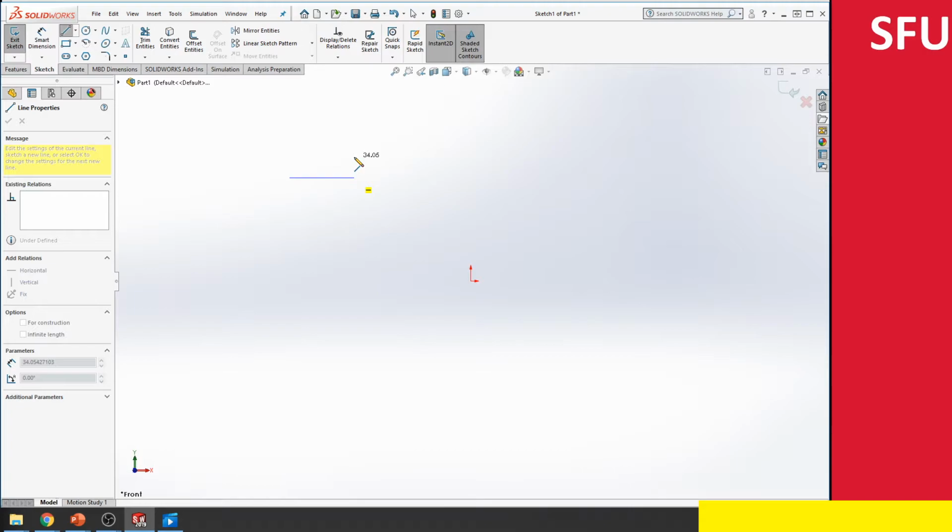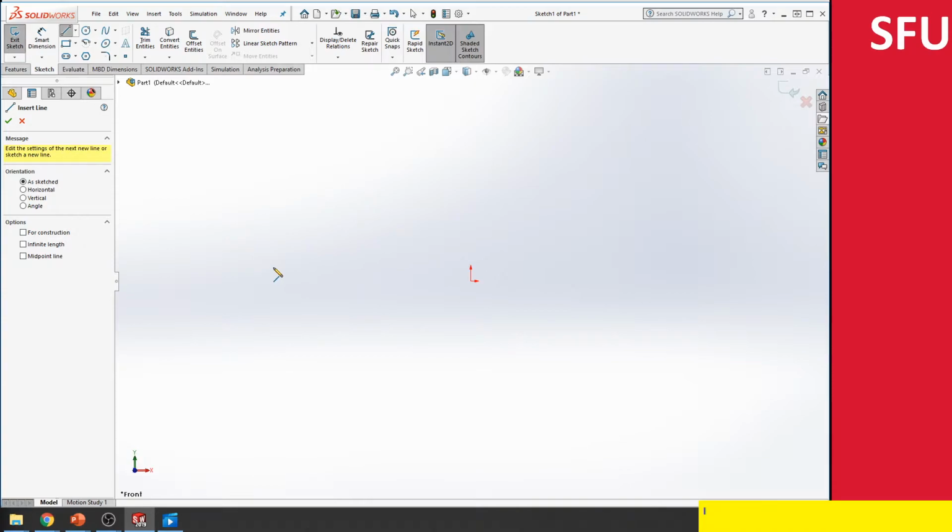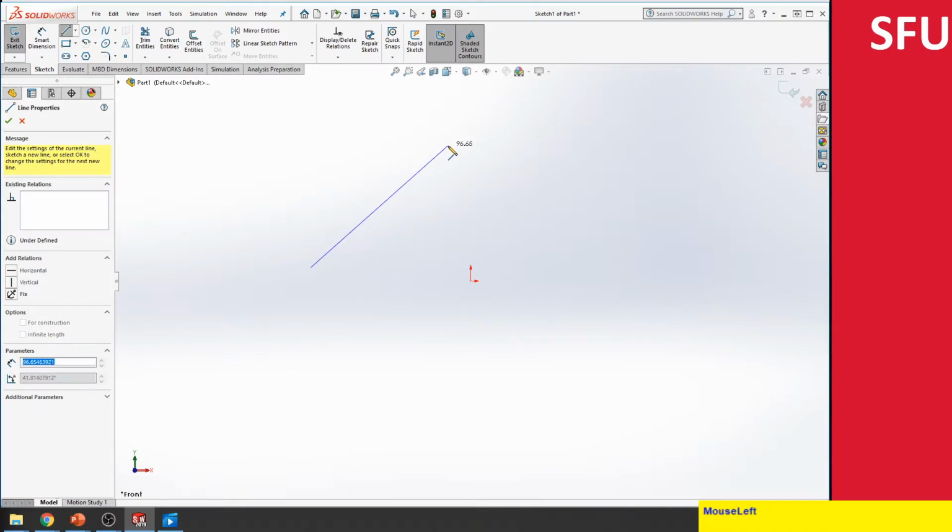So let's hit escape again, so that gets rid of this command. So do L line, now as sketched. I draw the first line, notice that I can continue drawing more lines, and then notice that as I get close to this, it's creating a yellow highlight. It's wanting to close the figure because it's assuming you normally want to do that, and then you close the figure, and now it gives you a closed figure over here. You can play around with the other options, but I'll just show the more interesting features over here.